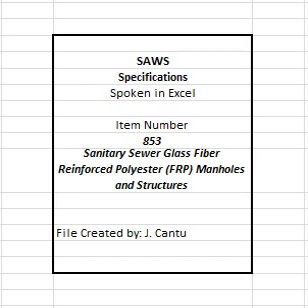10. With the valve closed, the level vacuum shall be read after the required test time. 11. If the drop in the level is less than 1 inch of mercury, final vacuum greater than 9 inches of mercury, the manhole will have passed the vacuum test. 12. The required test time is 2 minutes.